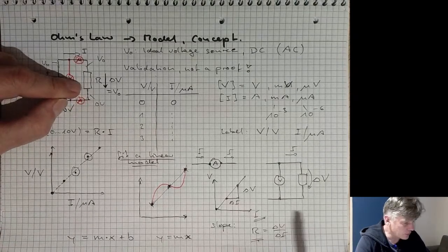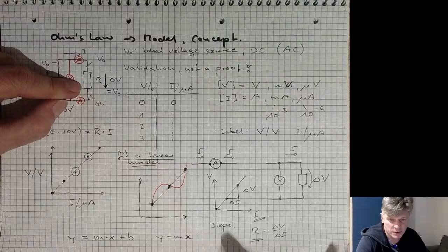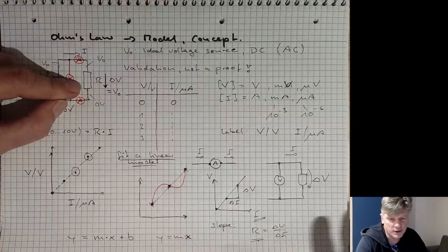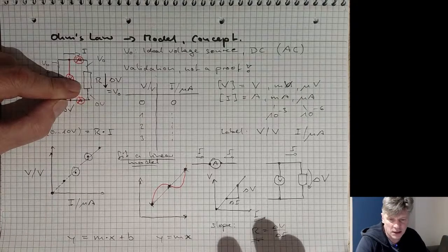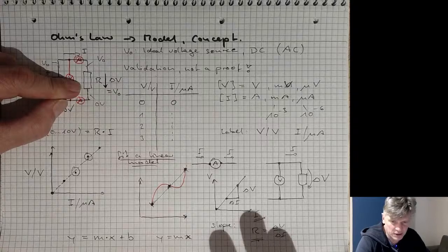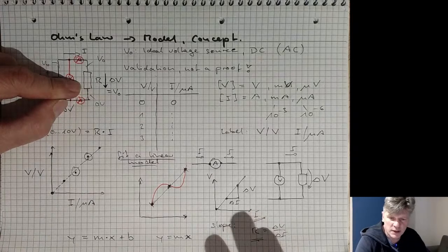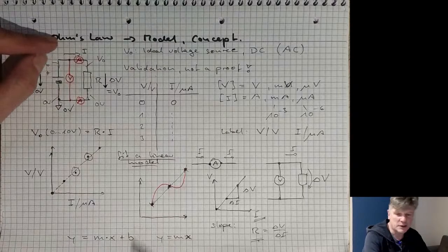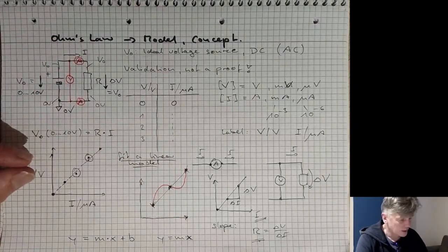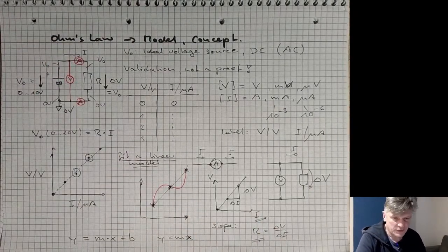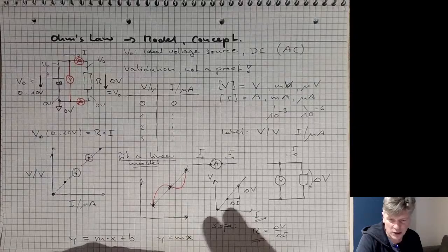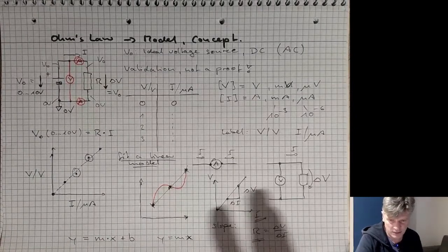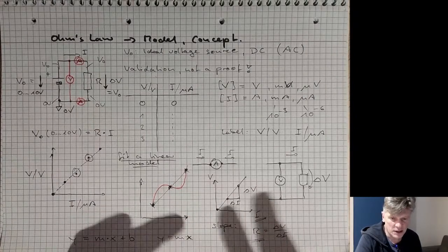So resistors get warm, or they can get hot, or they can even be destroyed when you increase the power much above the rated power of the resistors. So depending on the size of the resistor, they can dissipate more or less thermal energy. They can dissipate more or less thermal power.